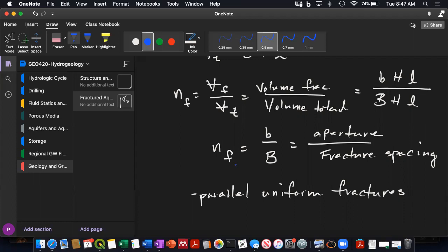Other ways that I've been involved that we are doing right now is injecting a fluid into the fractures and then looking at how that changes the electrical resistance. So if you injected salt water into the fractures and you measure the electrical resistance between two electrodes, you could potentially see that fracture as a really big, highly conductive zone.